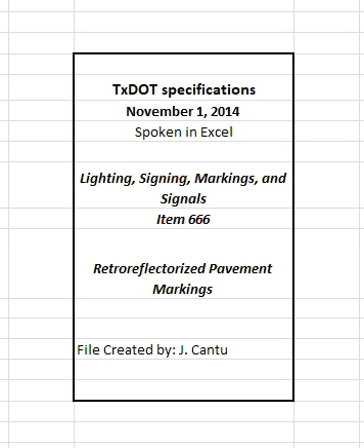It has either an internal global positioning system, GPS, or the ability to be linked with an external GPS with a minimum accuracy rating of 16 feet 5 inches, in accordance with the Circular Error Probability, CEP, method. CEP is the radius of the circle with its origin at a known position that encompasses 50% of the readings returned from the GPS instrument. It can record and print the GPS location and retroreflectivity reading for each location where readings are taken.